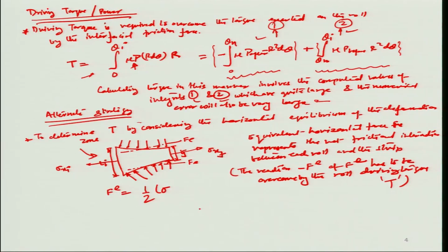So here half sigma xi times Ti minus sigma xf times Tf is going to really give the total forces on this element because of the torque. And you have to remember why this half factor here is because when we are talking about this particular element, all we mean by the coordinate frame is to look at the thickness, which is actually y equal to Tf by 2, and similarly it is Ti by 2 on both sides. So we are following the same coordinates here.